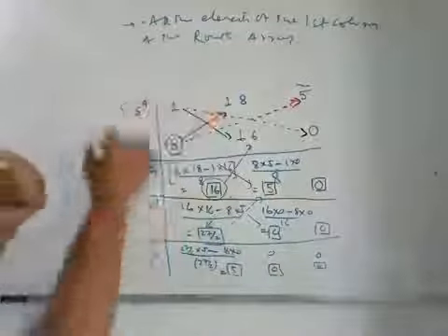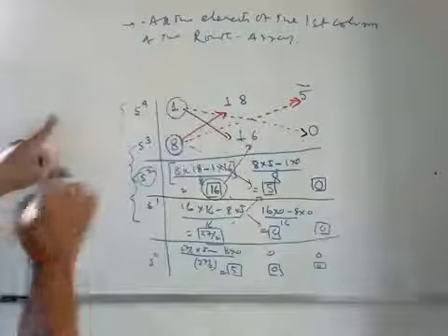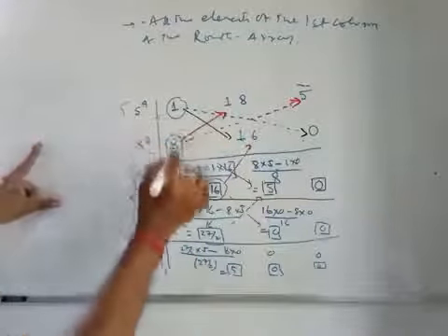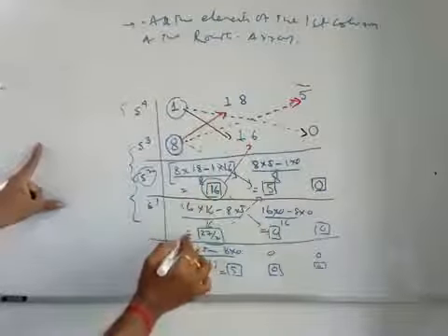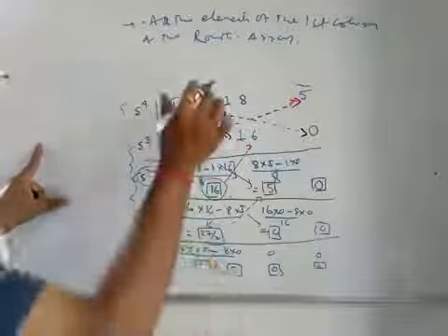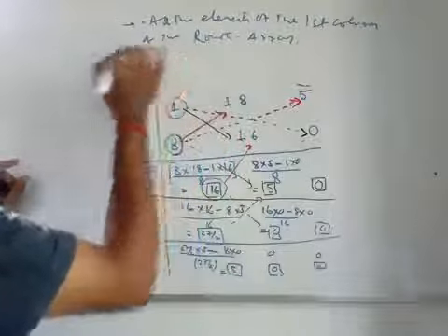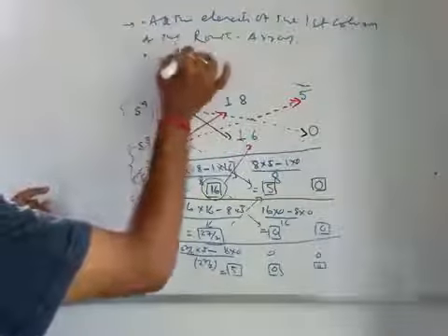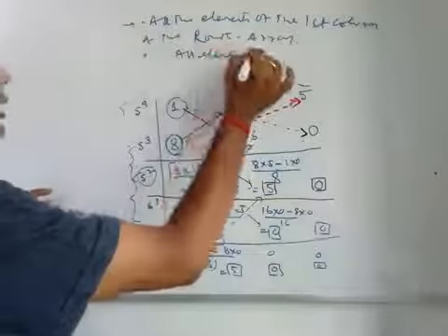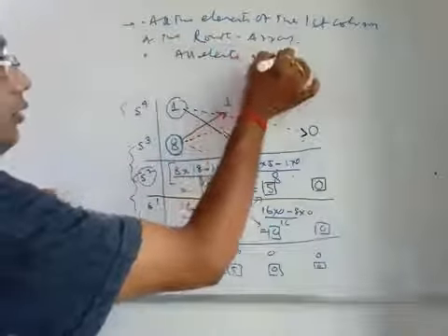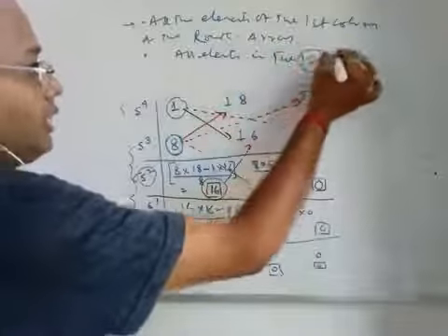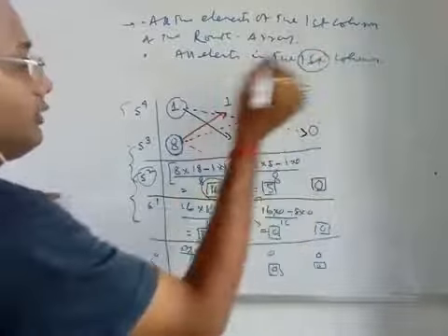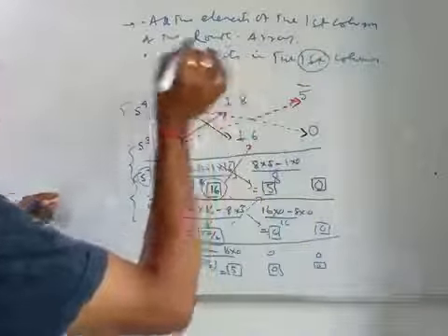So this is a complete Routh array. You check, this is plus 1, plus 8, plus 16, plus 27/2, plus 5. So what you have seen is that all elements in the first column, only the first column elements you have to consider, are positive.